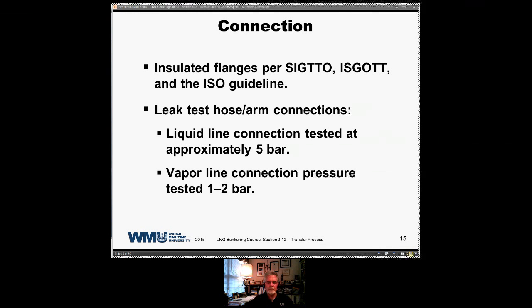The cam lock operation is a little bit faster than the bolting, and actually because you're controlling these locks hydraulically, there's usually equal force on these cams, and you're actually less likely to leak using cam locks than you are with bolts, because when you bolt up, there's usually 12 to 16 bolts.